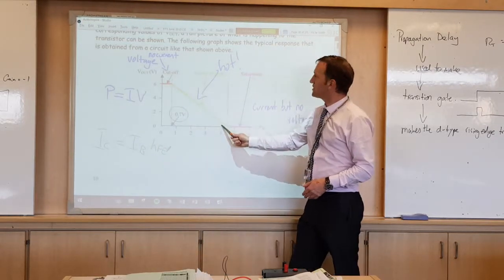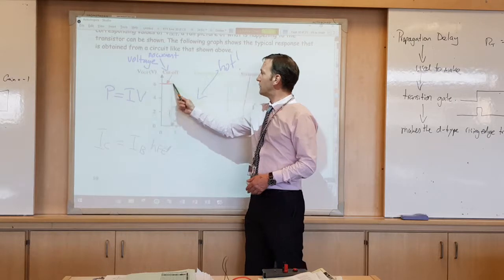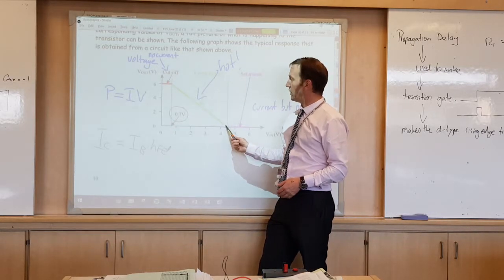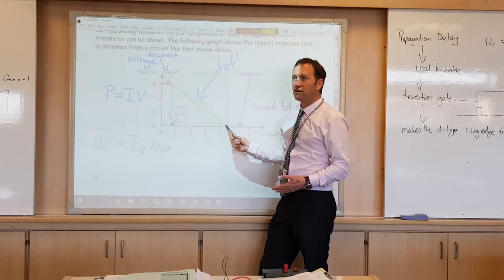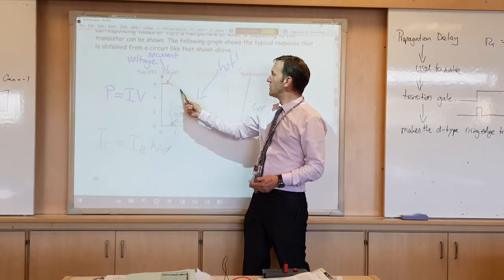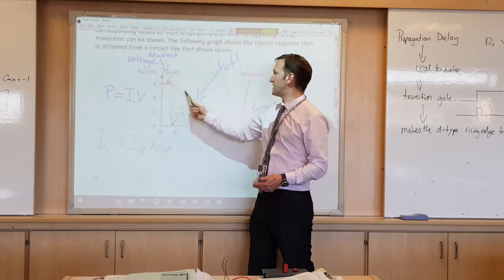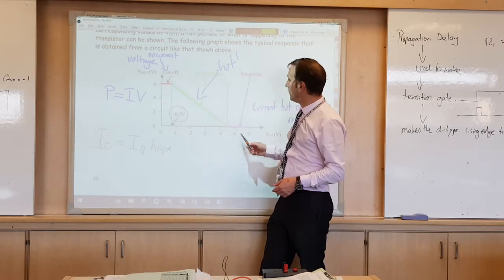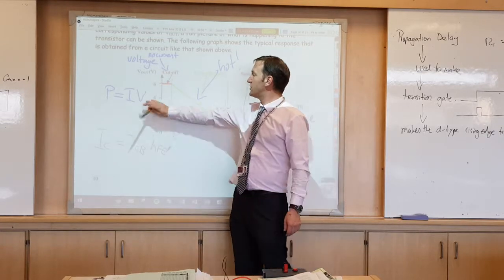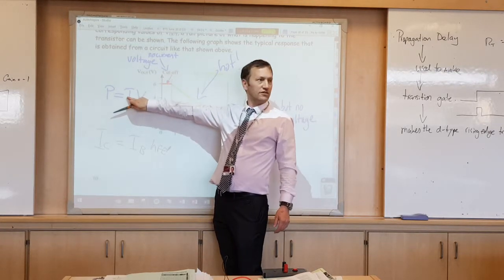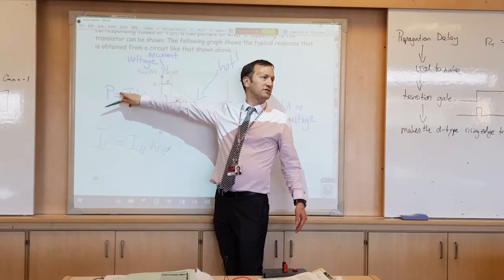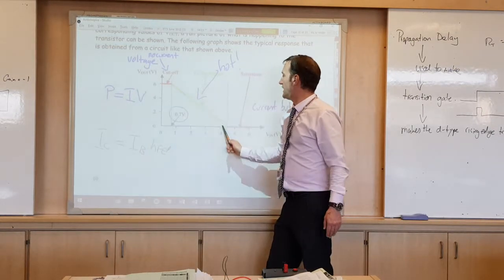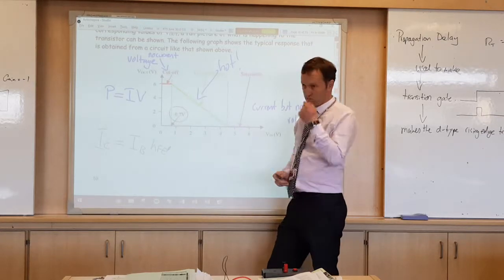Here though, we've got a mixture of Is and Vs. Here we've got a high V and a low I, but here they're half and half. And then down here we've got a low V and a high I. So either way, here we're going to have heat produced in the transistor. That's when they get toasty. When it's fully on, we've got no voltage, but we've got a high current. Still no power. So therefore, hot in here, cold and cold.